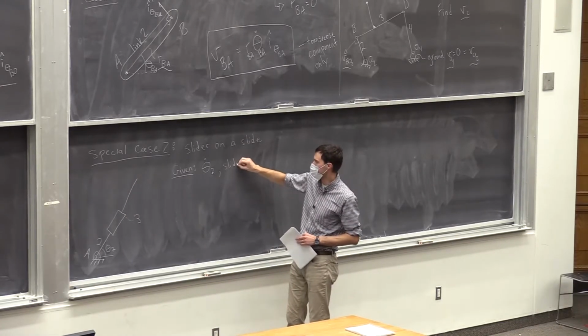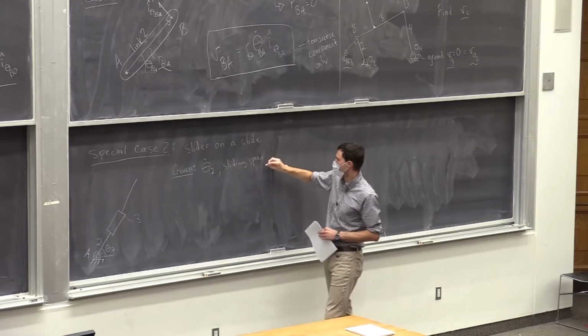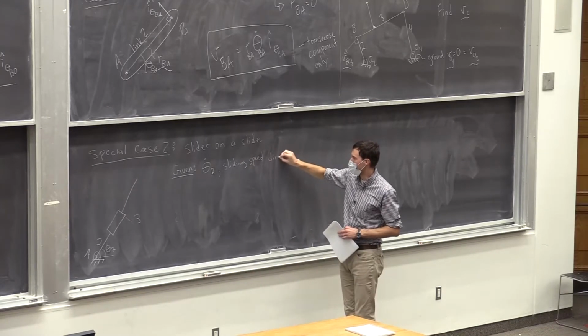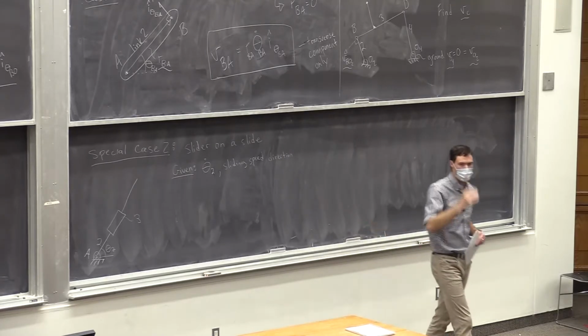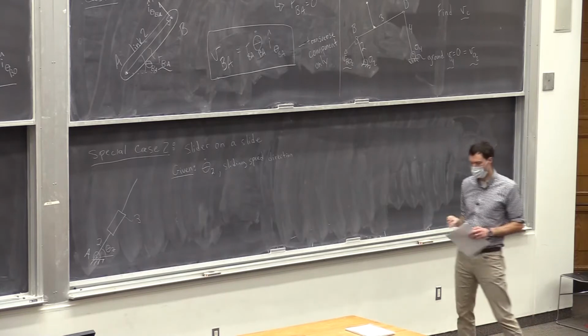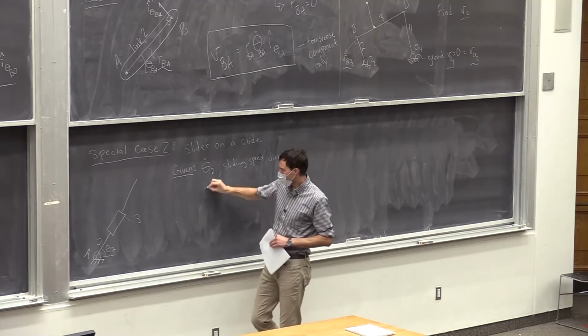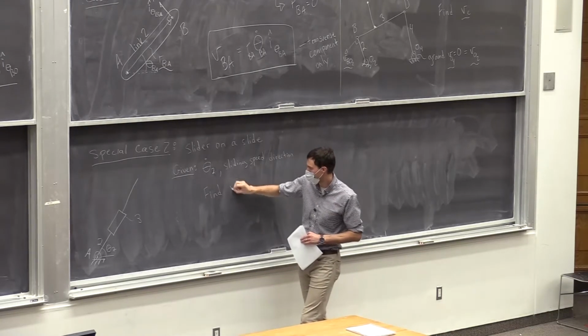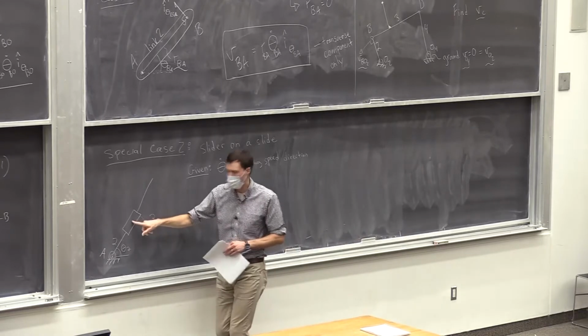So let's say we're given the sliding speed and the direction of the sliding, up or down. You can imagine 1 meter per second sliding up the link 2. And our task is, let's find the velocity of the slider, of something on link 3.